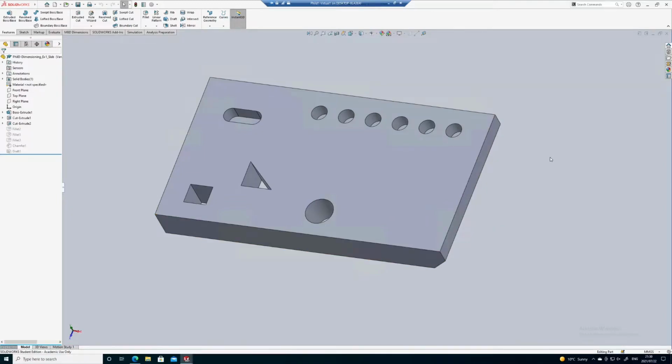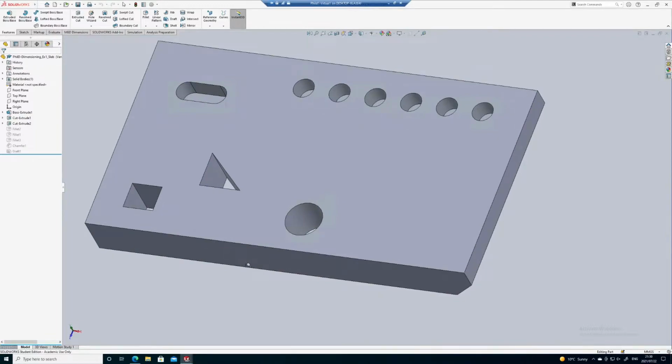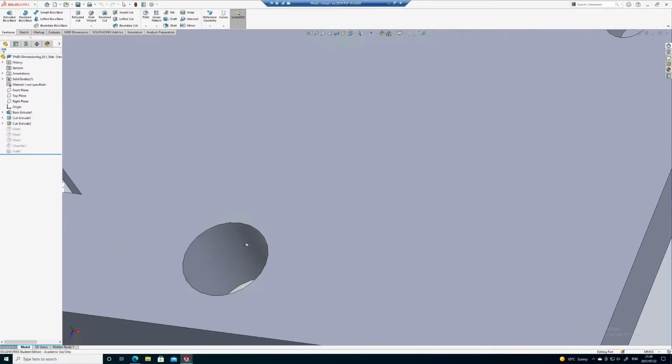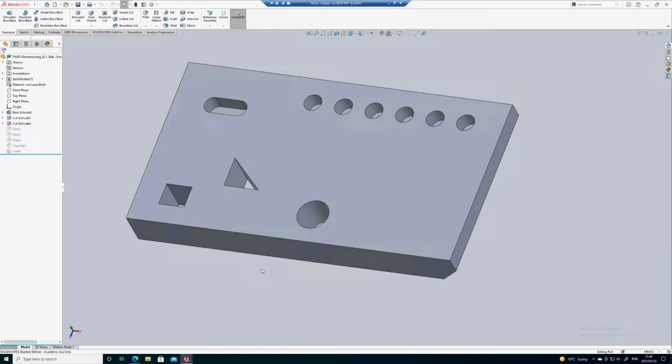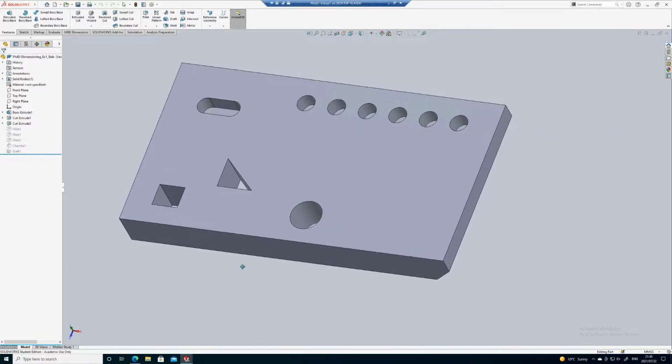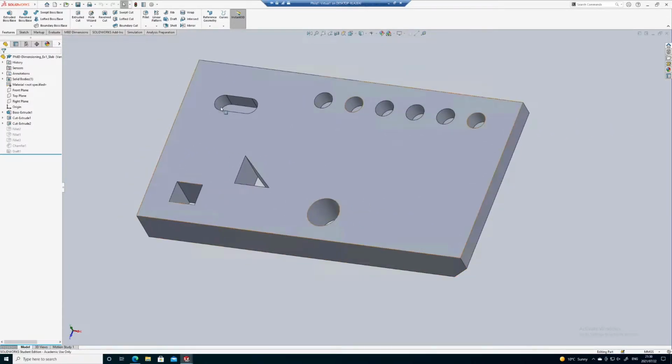If I can remember what it was that I skipped out on recording this afternoon. I know that part of it was just the shortcut keys. If you hold the shift button down and the middle button down, or click the middle button, you can drag. Like I'm dragging upwards and it's zooming in fast. Drag downwards, it zooms out fast. If you hold the control key and click the middle button, you can pan left and right pretty fast. So if you didn't know those, now you do.